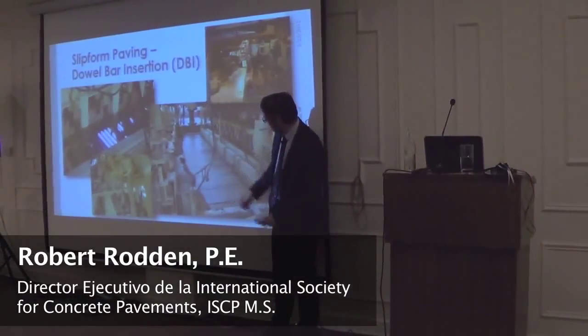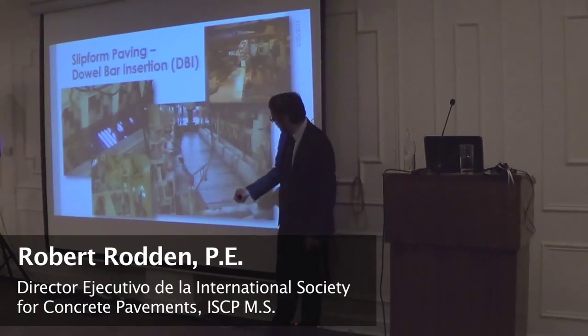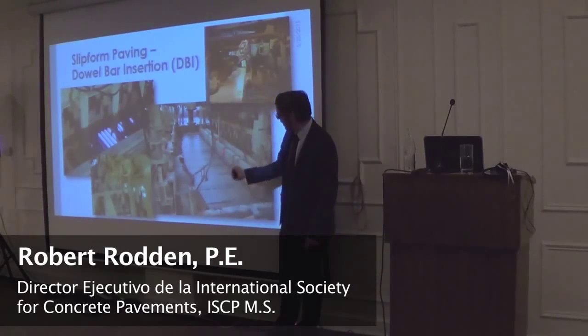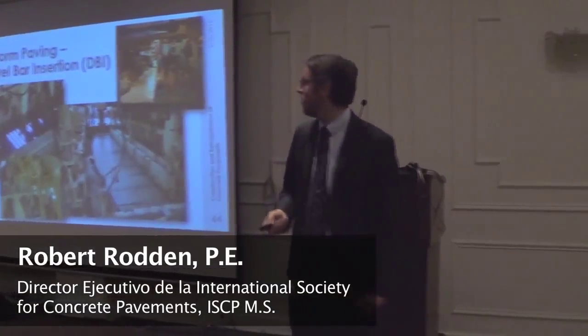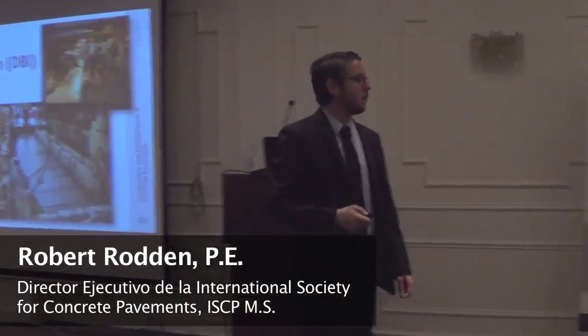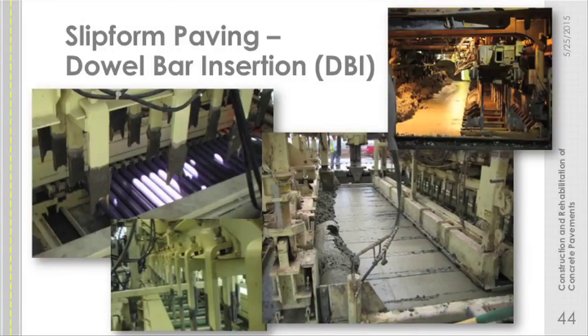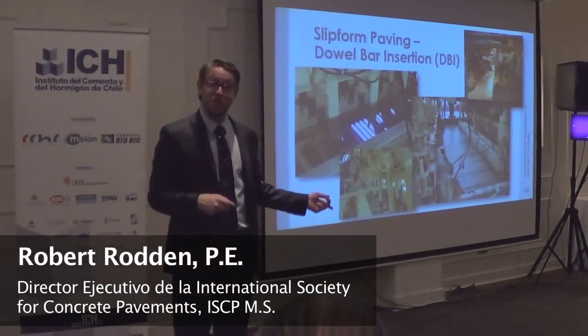So in the end, the system gets closed up due to the vibration, about like this, and it's enough that the pan then will close the rest of the way. It's a very cost-efficient way of building doweled concrete pavements. And we've found through experience that while there needs to be a very well-graded concrete for all of this sort of vibration and placement and vibration back out to work correctly, the alignment that we get with these systems is actually better than with baskets.